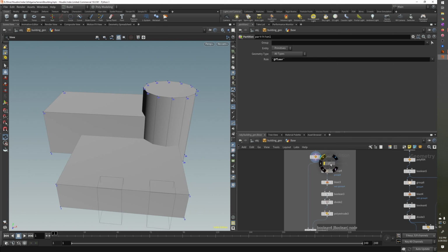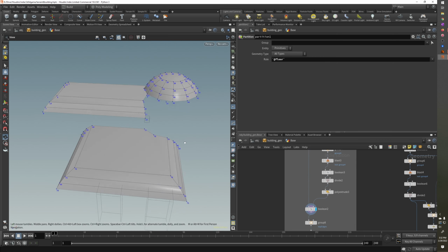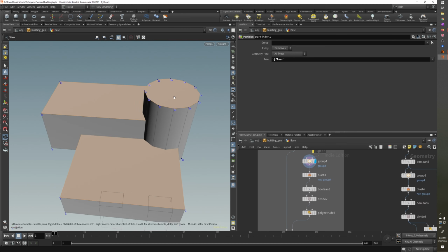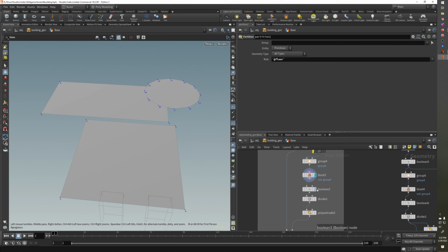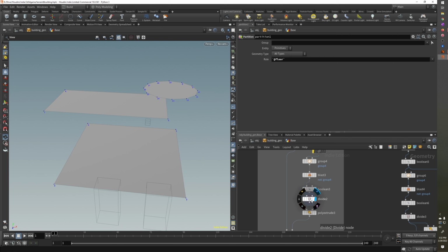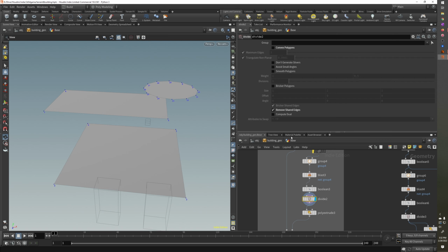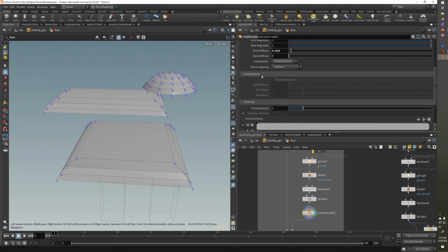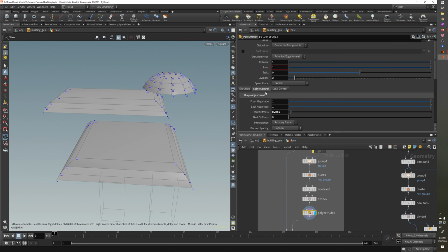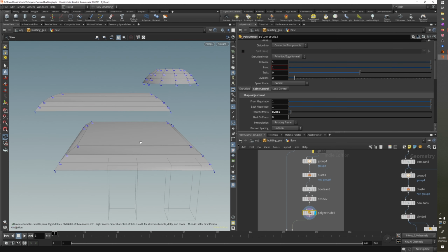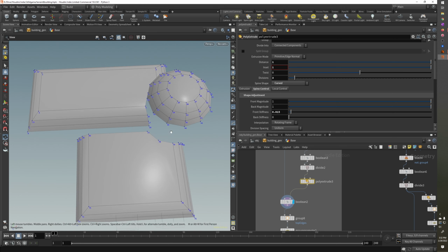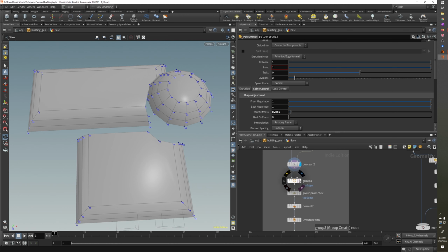And then we do a Boolean of this original geometry against one where we take the top faces, we blast everything else, we Boolean them together in case there's some overlapping faces, we divide them and we get rid of shared edges so we just get flat shapes, and then I just poly extrude them up and add a bit of a curve with some spine control stuff, add a few divisions to it so it looks nice, and then yeah, just Boolean it against that original shape so it fits basically perfectly to what shape we had.